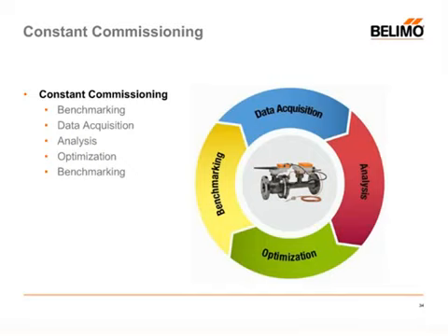You would have the opportunity to select what the desired delta T for operating and optimizing the coil would be, based on that analysis that you've actually executed. And then you're back to benchmarking again. At the end of the cooling season, you'd say, all right, this is the way my system is. How does it compare to what my system was at the beginning of the season? Has there been any degradation? If there has been, how much has it? Quantify it, and maybe you can actually take some action based on what you see.